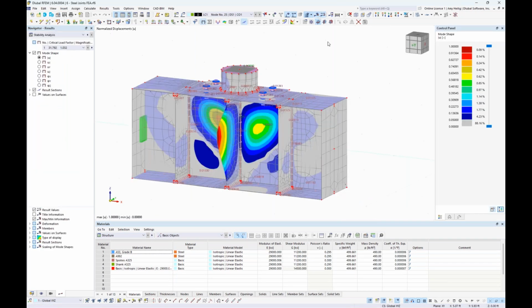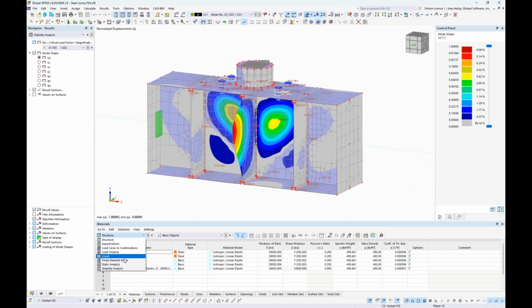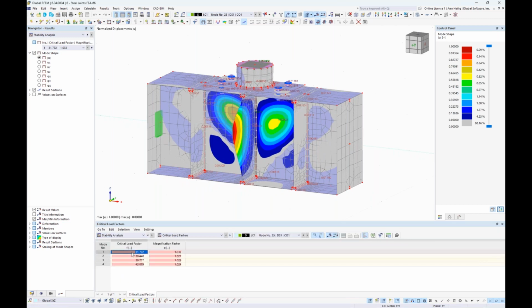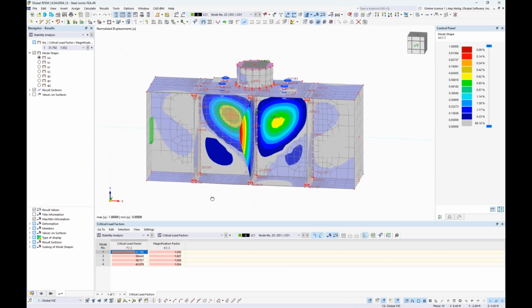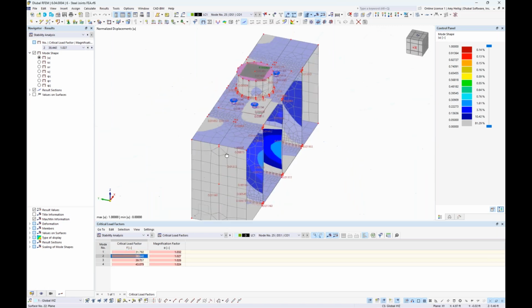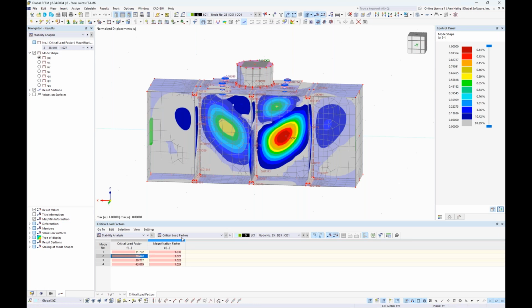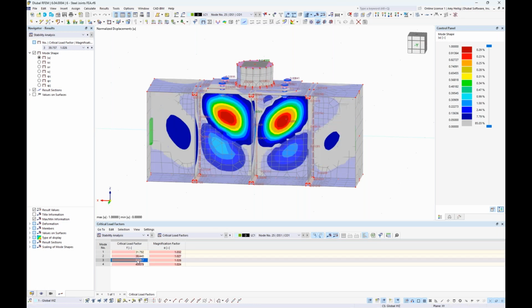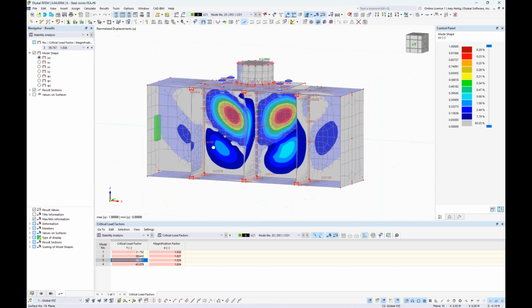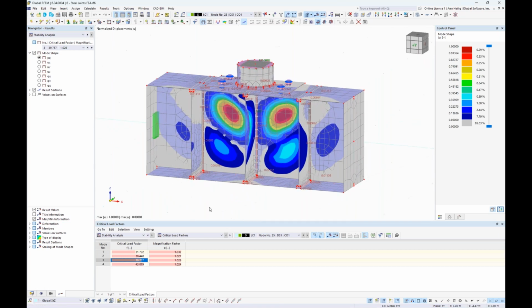So every example that we've seen up until now is the same workflow that's going on underneath the hood, where we can view here under the stability analysis results are 4 different eigenmodes, the critical load factor of 31.729 before we see kind of the buckling of that stiffener plate, and then also the relevant mode shapes here with slightly higher critical load factors. So again, we start to see concern for the buckling of these web elements. So pretty unique and powerful, again, about what's going on underneath the hood for any connection type because of the ability to generate this FEA.